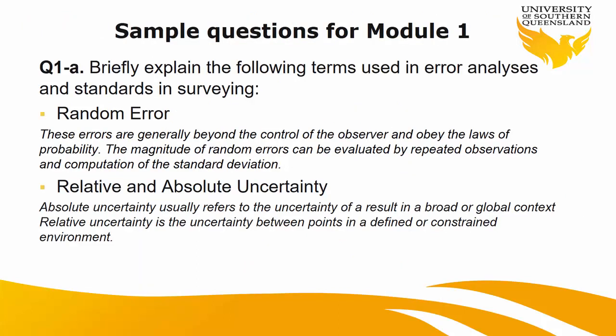So it can be, for example, this type of question. I tell you, what is random error? What is random error, by the way? Anyone remember? Let's test you. We have systematic error. We have random error, yeah? Systematic error is you forgot something, yeah? You forgot to put the prism constant or something. You didn't measure the height of target very precisely or something like that. So everything is going to be out by a constant number, yeah, or something.